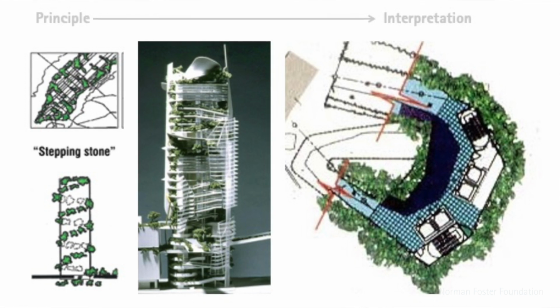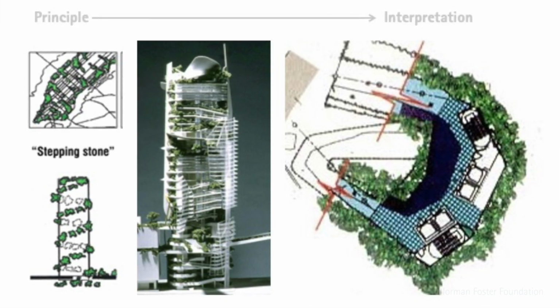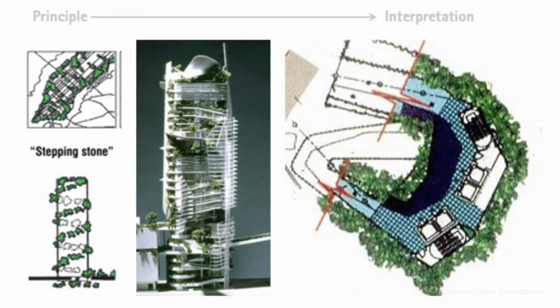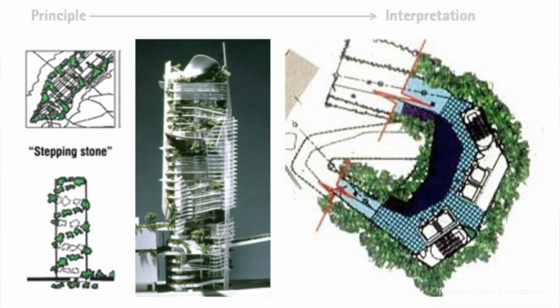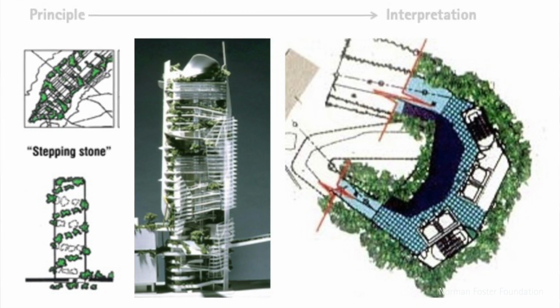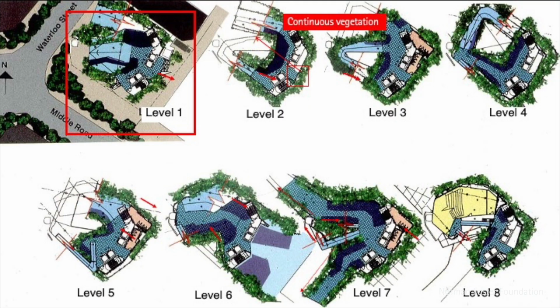And so here's some illustrations of how this could be implemented in architectural design. Back to this project that we did. This is the tower back in 1985, and you can see the plan. On the left-hand side are studies that show how the core position can contribute towards designing a low-energy building. Now, what this diagram shows from all these orientation, configuration, whether it's a central core or a side core, is that the core on the east and west sides in the tropics reduces its energy consumption.